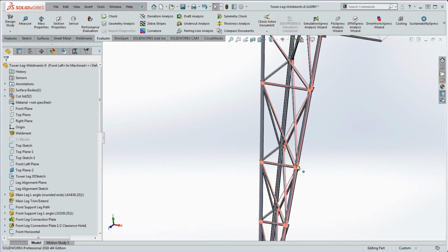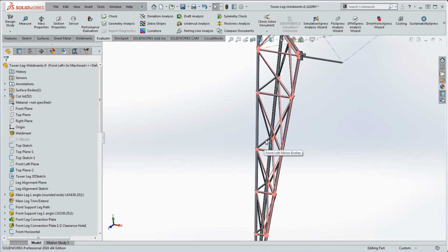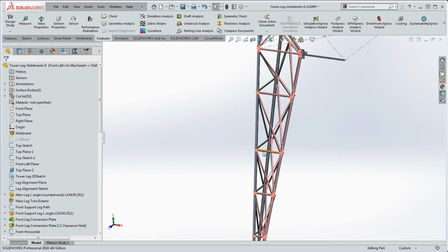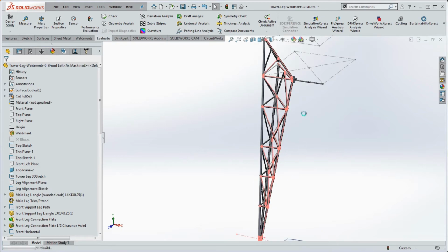This diagonal, that horizontal over here, the connection plates that we have in the background, everything that's connected to that gets stretched too. And that becomes even more dramatic when we actually take some of the elements in here that are associated with the structural member path segments. When we change the dimensions on those, it changes it too. So that's going to be a second way we can change our model. And of course, if you do Control-Z, you can see how that changes. Kind of takes that back to where we were before. And again, all these elements that are coordinated in here get changed too, and everything gets updated and still stays coordinated in a very stable model.